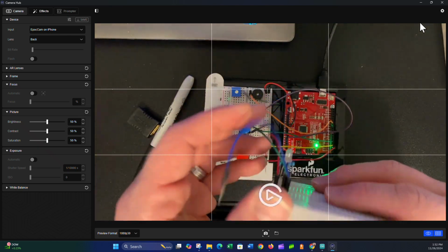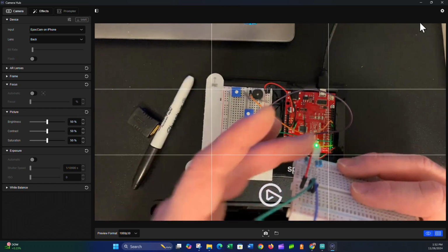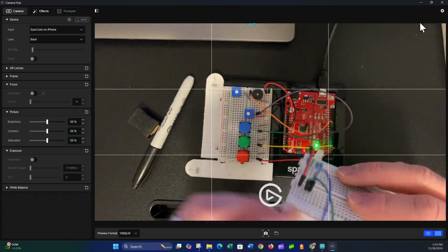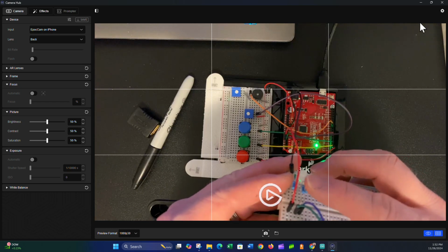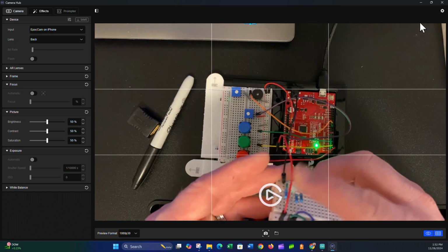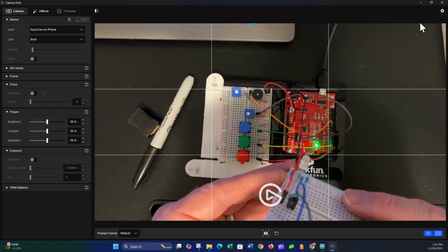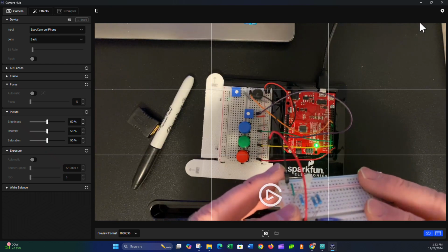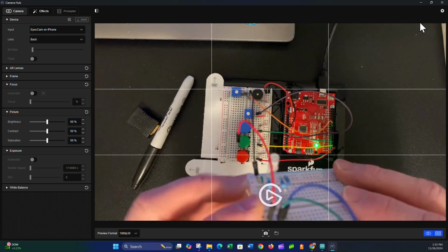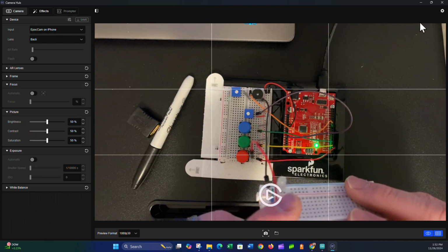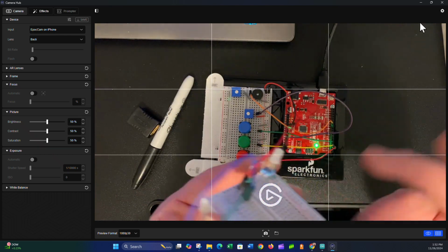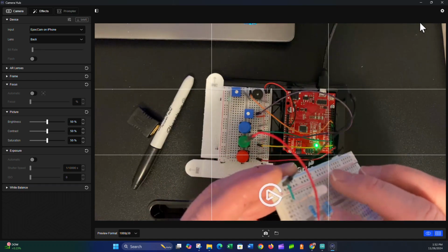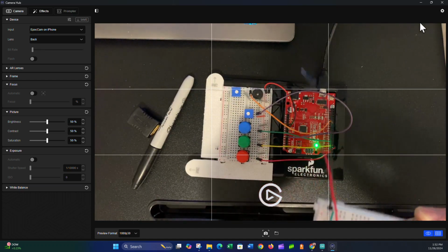And I've shown those connections with the appropriate colors, red, green, and blue. Because they are all individual LEDs inside this one RGB LED housing, they still need resistors just like any LEDs do to limit that current, so that you can protect the sensitive LED. So these are 300 ohm resistors. You could use 330 ohm resistors, but I happen to have some 300 ohm resistors, so that's fine.